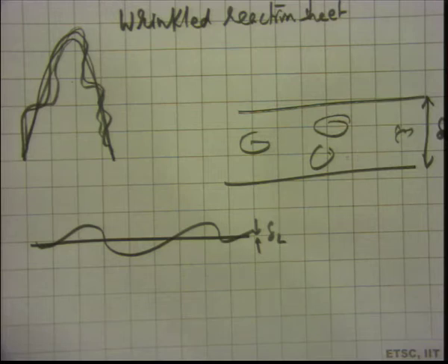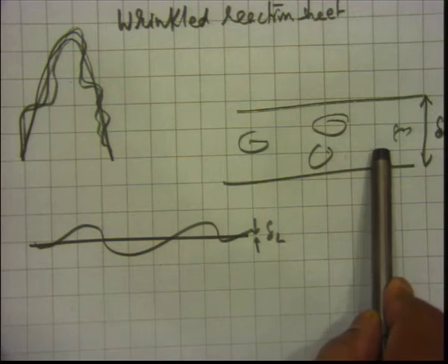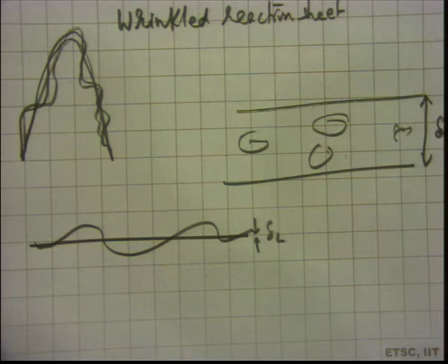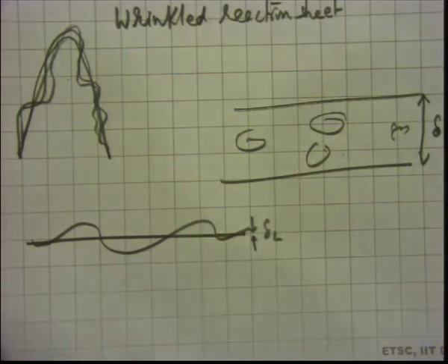Maybe the reaction rate is small, that is why delta L is large. See, here we are in this situation, we are saying that the delta L is large. Why is it large? Maybe because it's a fuel which is not very reactive, or maybe it is not even a combustion reaction. This is a reaction with something else, pollutant formation reactions. See, NOx formation reaction, for example, is much slower than a hydrocarbon combustion reaction. So, maybe it is some pollutant, it is not exactly a flame, or maybe this is for a fuel which is not reacting much.